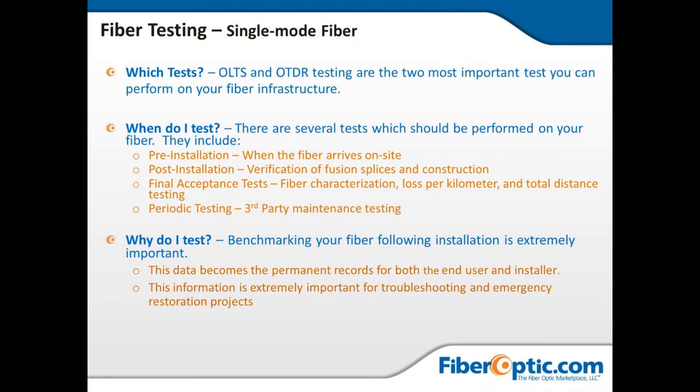And then the last bullet here says third-party maintenance testing. Periodic testing of a cable plant is important. Whether you're a third-party provider means periodically you go out and you shoot the circuits. And it's like taking an MRI at a hospital. You go to a doctor and he says, I don't know what's wrong with you. Here, go take this MRI. Well, they're taking a base shot. That's your final acceptance. I need a baseline. You could come back 3 years later. The doctor 6 months later gets your MRI back and he goes, what ails me? He goes, you should have been here sooner. But anyway, the third-party maintenance can show you deterioration in your system long before it takes you down.